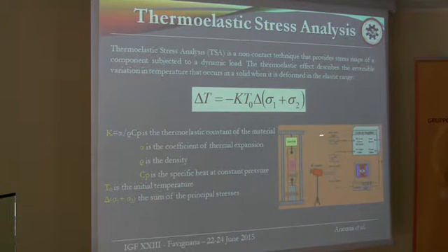The typical setup of thermoelastic stress analysis consists of a loading machine, an infrared camera, and a lock-in amplifier that is able to process the reference signal from the load cell and the signal of the detector on the camera in order to obtain our analysis output, like the amplitude of the signal and the phase shift.